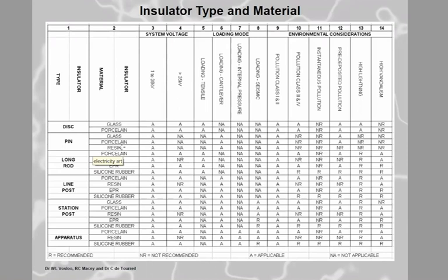That reduces its wet flashover voltage by about 20%. You will find that once the material is subjected to high humidity and localized arcing, it will break down quite readily, and it will be due to hydrolysis. So there's an inherent problem. It's not to say you can't use it, but you will use, for instance, cycloaliphatic at 38 millimeters per kV, where you would use porcelain at 31.